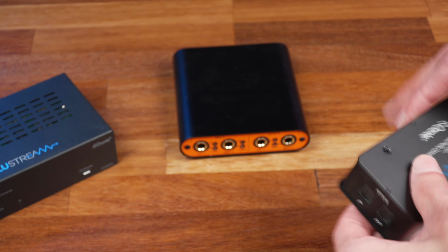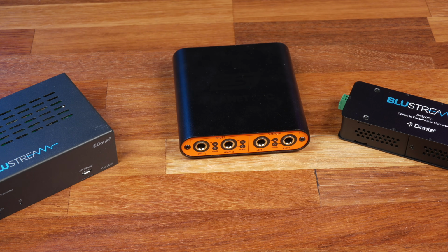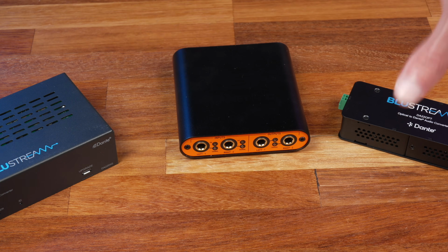Now, as for why I particularly went for an optical interface over various other options, it just seemed like the safest bet. It removes a pair of additional analog to digital conversion steps compared to using an analog Dante interface, and whereas a lot of TVs will mute their speakers if you connect something to their headphone output, they don't do that with optical audio. So that means it'll make it much simpler to switch between the multi-room system and the TV speakers just by muting or unmuting the TV's volume.